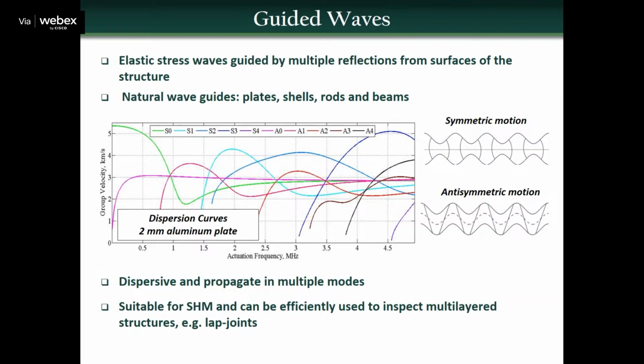Here you can see that at different actuating frequencies, the group velocity will change over frequency. You can also have different modes showing there, from S0, S1, S2, S3 to A0, A1, A2, and so on, for symmetric motion and asymmetric motion as shown here on the right. The guided waves are dispersive and they will propagate in multiple modes even at the same frequency.